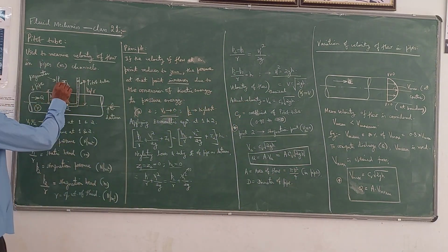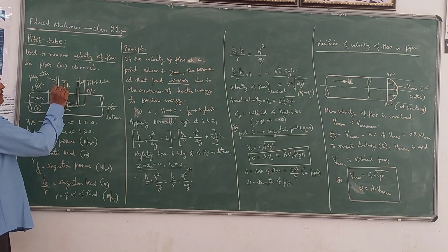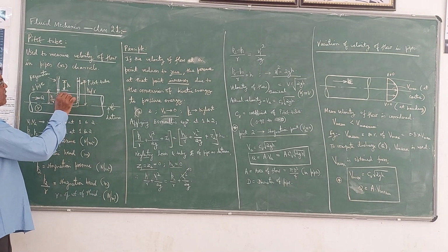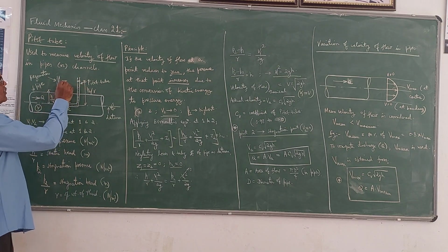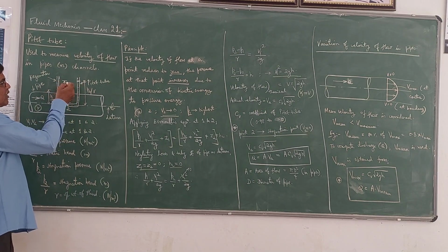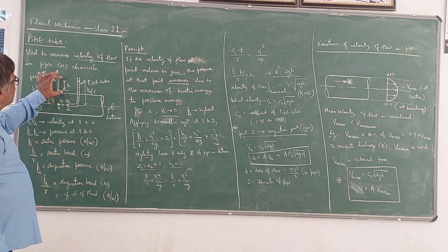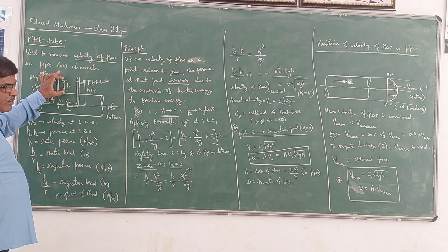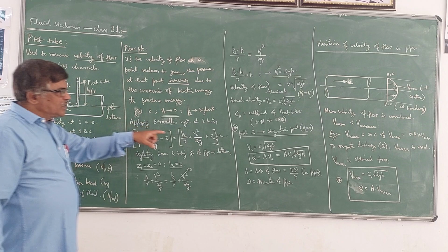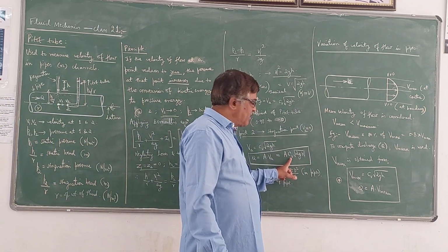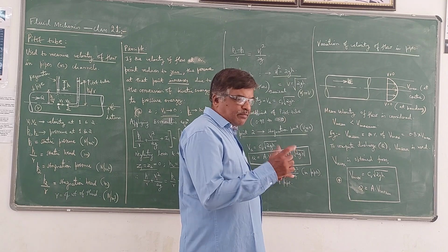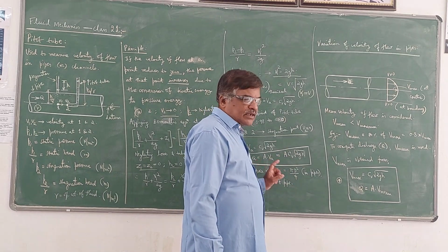So finally, by knowing only one value, that is the small h value, if you can measure the difference between the levels of the liquid flowing in the two tubes, that is one in the piezometer and one in the Pitot tube. So if you measure the difference, for example it can be 20 mm or 30 mm, then just by using that h value, knowing the Cv value and the area of the pipe, you can compute the discharge.